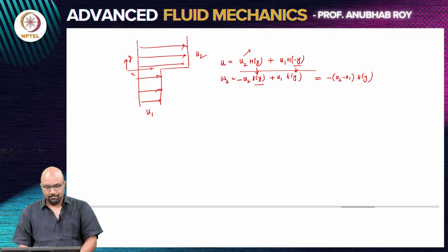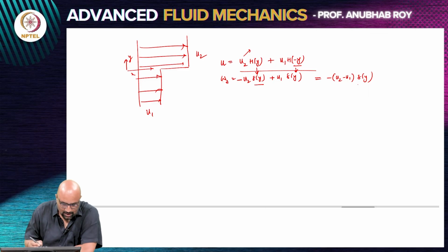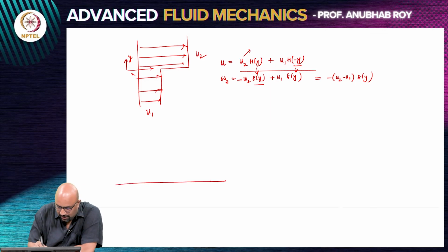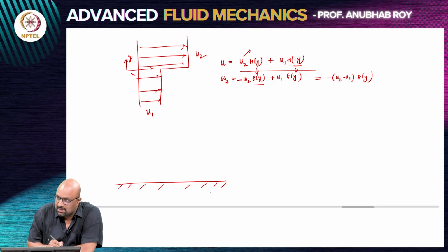So this is how it's interesting to study more about unsteady flows, what goes on in unsteady flows and how they behave. Now, the problem that we did, an impulsively pulled plate problem, didn't have any inherent length scales or time scales in the problem, and so we got the similarity solution.